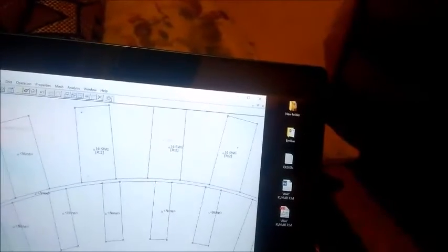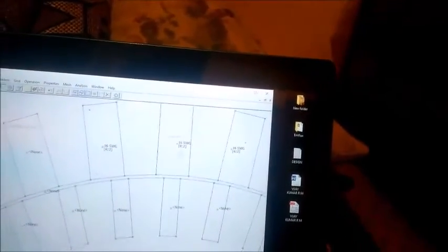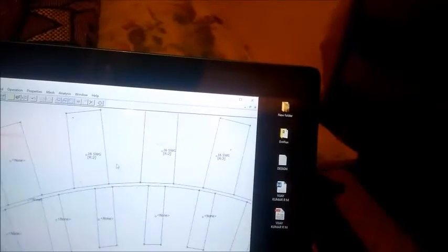Now you can see I have taken 3 slots per pole, so this is R phase and 2 turns per slot, that is totally 6 turns per phase. Similarly, now go here, you can see the gap, so go there and add a material here and click OK.